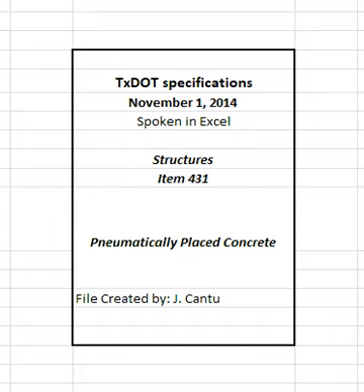Provide pre-bagged concrete materials for concrete structure repair and class of concrete shown on the plans for other work unless otherwise shown on the plans. Submit pre-bagged materials information for approval. Material testing may be required before approval and installation test panels will be required in accordance with Section 431.2.4, Proportioning and Mixing.